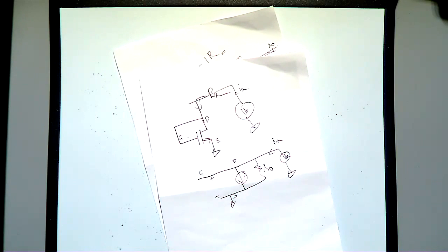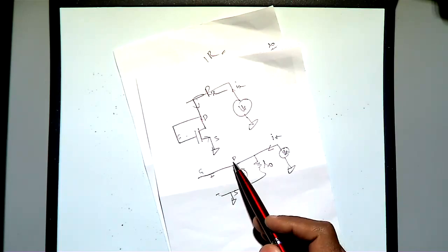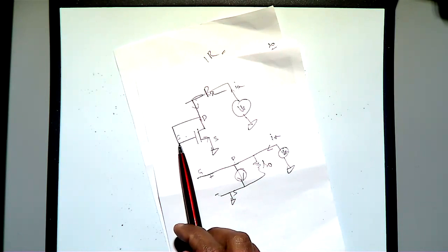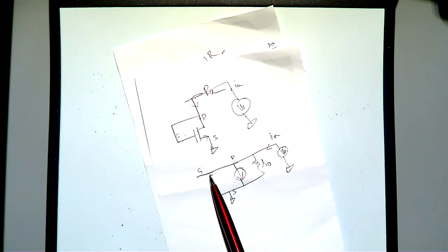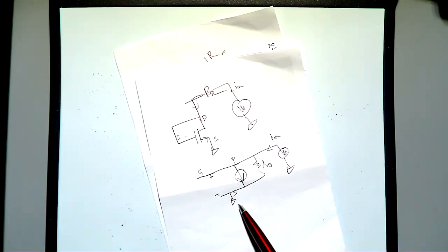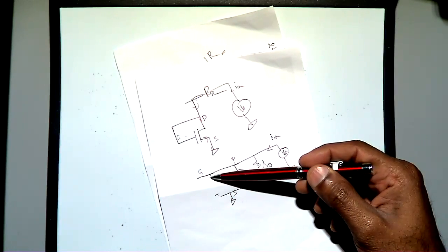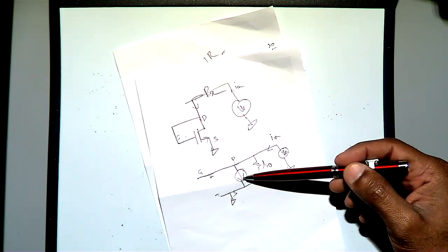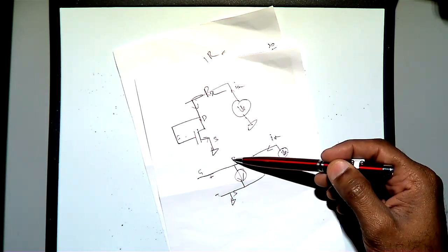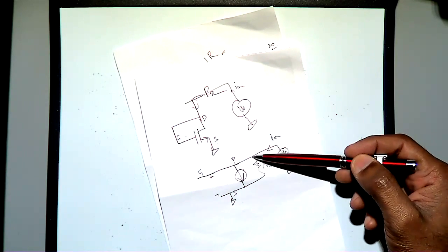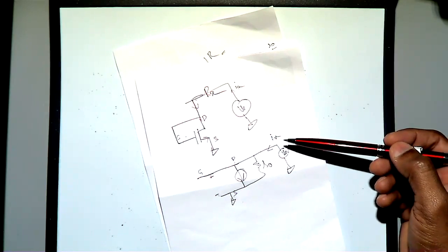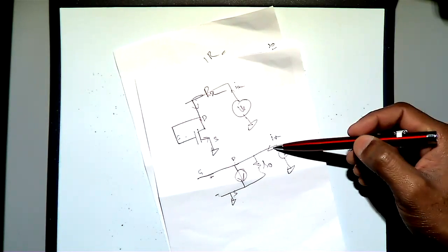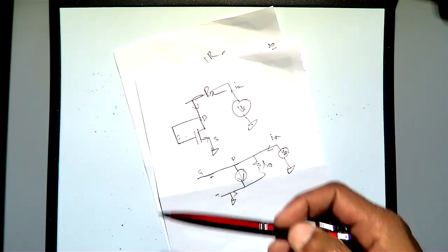See, I showed the drain and gate connected. So if you look from here, you check the gate, you get infinite impedance, and that is the reason it is open. Then the source is grounded. Then you can put positive, negative, or negative, positive. I put positive here, negative here, so the arrow is down. Then that is the drain. If you take into account the early effect, you get ro. Then in order to find the output impedance, we connect a test voltage source Vx, and we pump Ix current, and we short the input if the input is open.